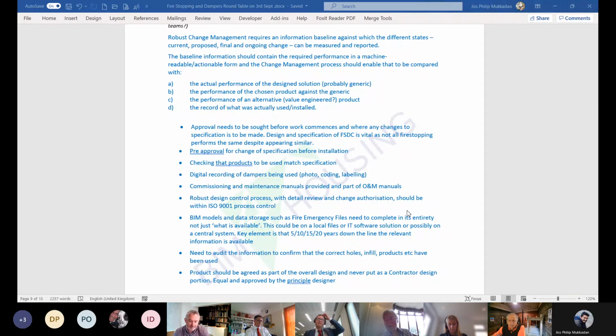Yeah, would it be right to say that people don't put ductwork through beams now on projects? They shouldn't. But as Paul would tell you, this is what I'm saying about the safety cases, is that if the MEP consultant's not an expert on what's been tested, neither is the structural engineer, who just says I want a performance of 550 on a beam, or maybe they'll go 620, and that will be it. The fact that the MEP's coming through it, the services like your ductwork and your dampers, isn't something the test standard accounts for, so you cannot install them in it. That is the bottom line.